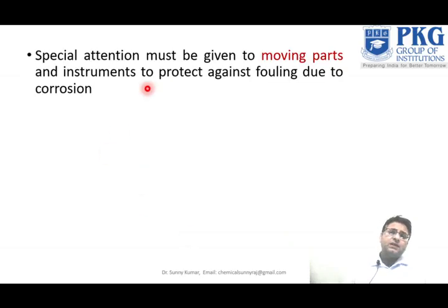Special attention has to be given to moving parts and the instrument to protect against fouling due to corrosion. Sometimes the instrument is also moving, during the agitation, so when corrosion happens, the part will break and come into the solution also.